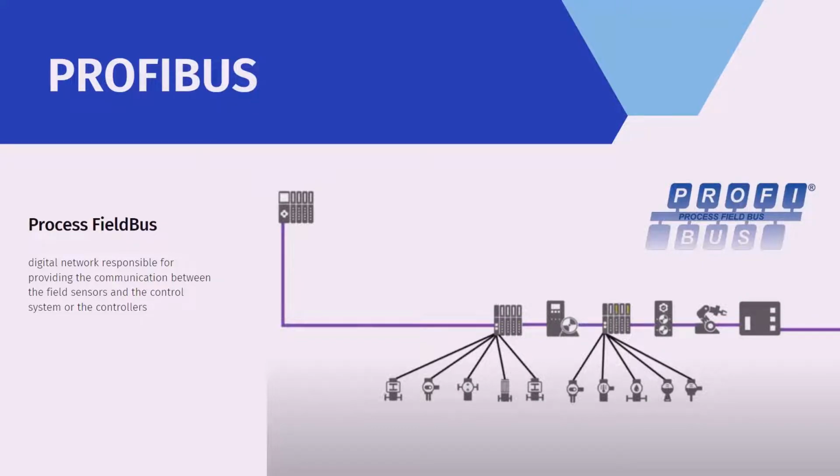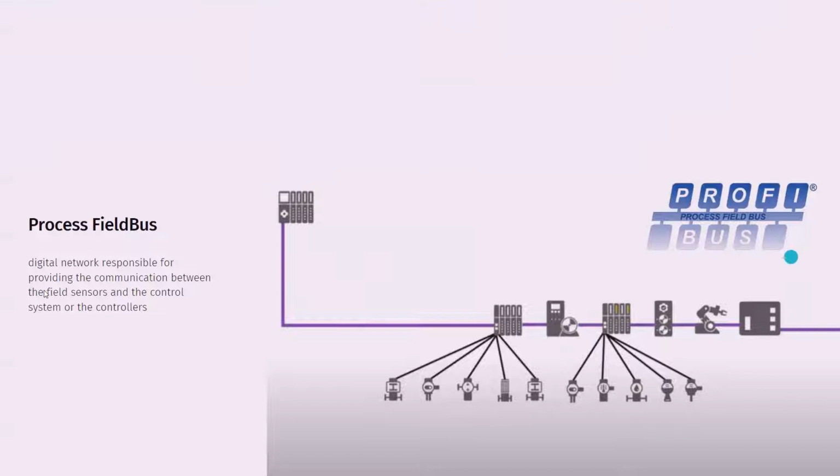Profibus has three variants: Profibus DP, Profibus FMS, and Profibus PA. The Profibus DP is one of the two variants that is used the most frequently. For this reason, it is regarded by many experts as the standard Profibus. It is used in process automation of large assembly and material machines, and supports single cable wiring of multiple inputs like sensors, pneumatic valves, smaller networks, complex intelligent devices, and operator interfaces.